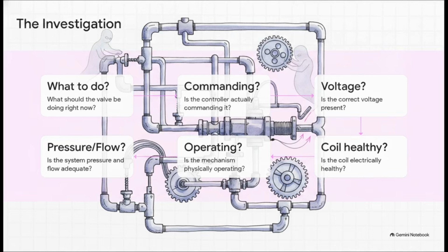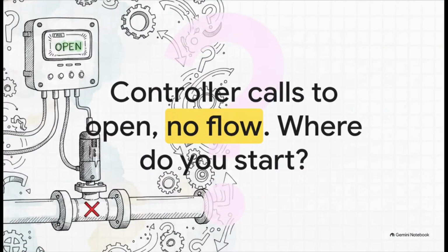We use this exact deductive stepping for a very specific reason. It prevents us from chasing ghosts. If you start unbolting the valve body before verifying the controller is even sending a signal, you are going to waste hours of your day. No one wants that. So let's pose a practical mystery to test this out.